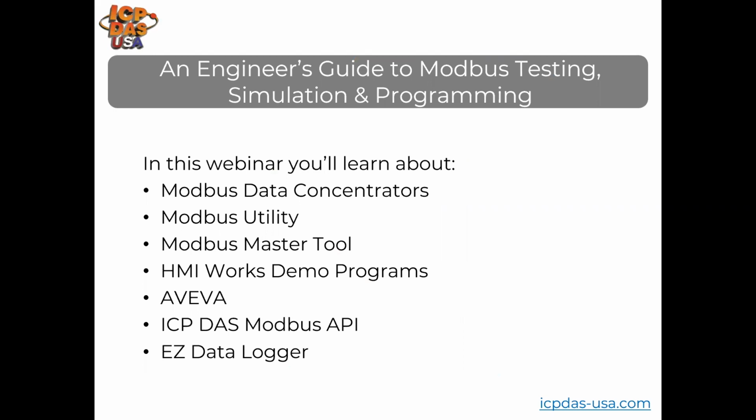I will be introducing Modbus data concentrators that perform up to 200 Modbus RTU commands for reading and writing to Modbus slave devices and allow Modbus TCP masters to get the pulled data over Ethernet. I will be going over some free tools developed by ICP DAS for configuring and communicating with Modbus slave devices, including Modbus Utility and Modbus Master Tool.